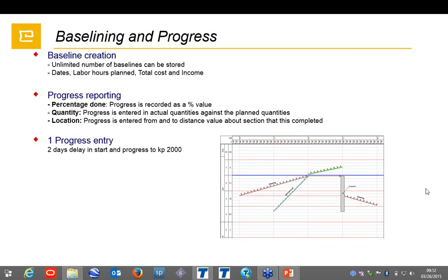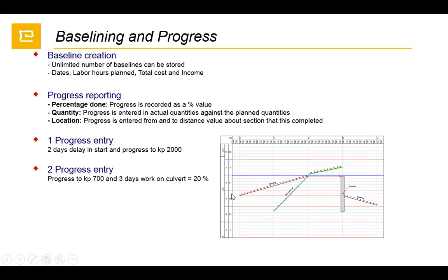And when there is a new data date for the second progress entry, now the data date is just moved to the next week, and we can see here for the progress it is splitting the task, so it will allow you to work with this task. For each part you are able to put actual start and actual finish. So this is also an advantage in the system.